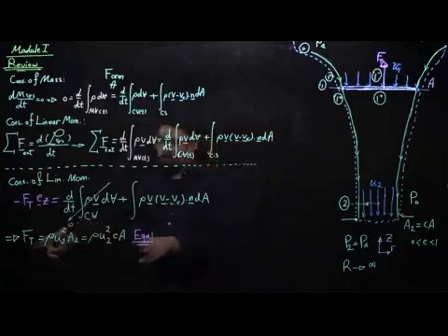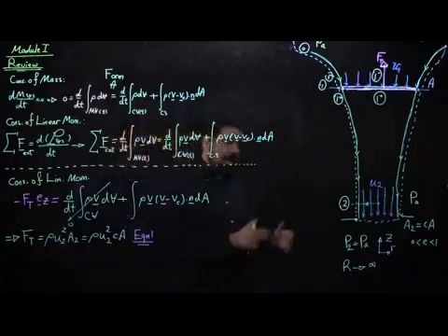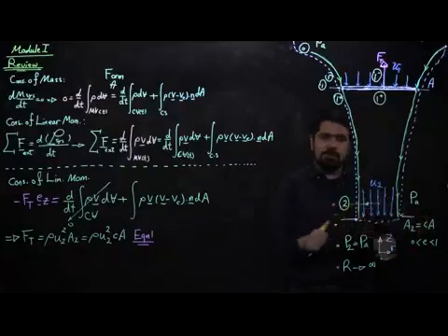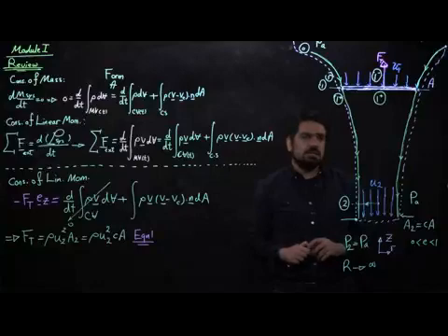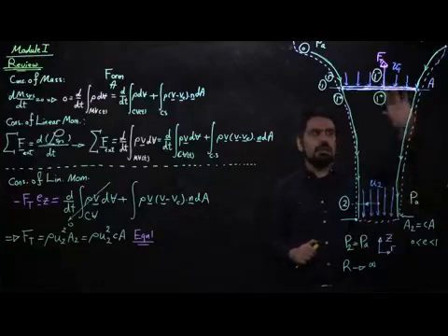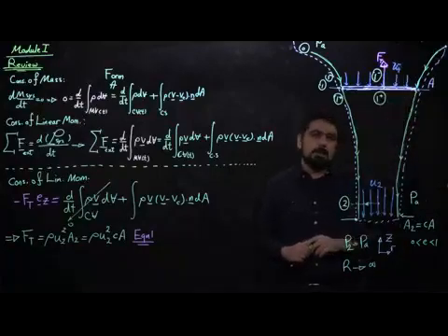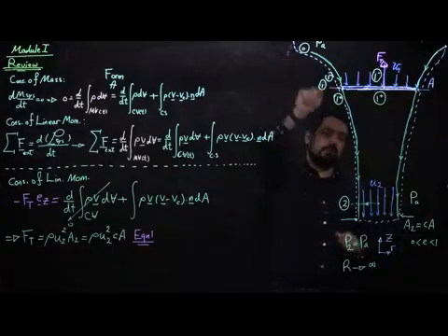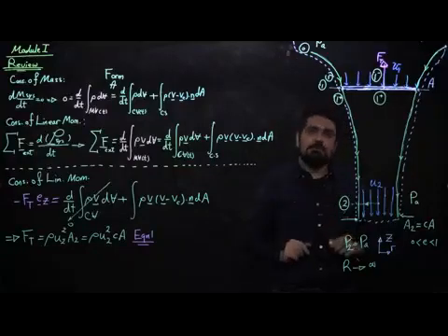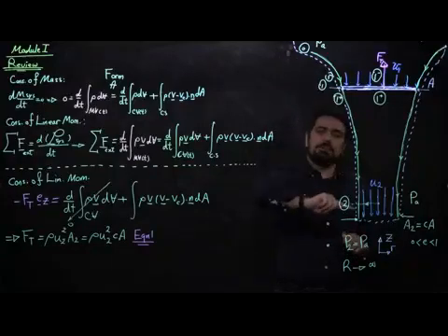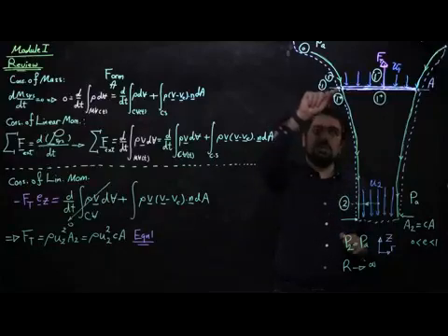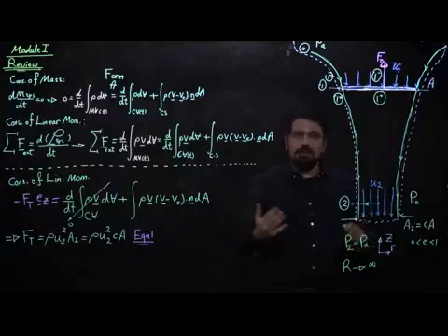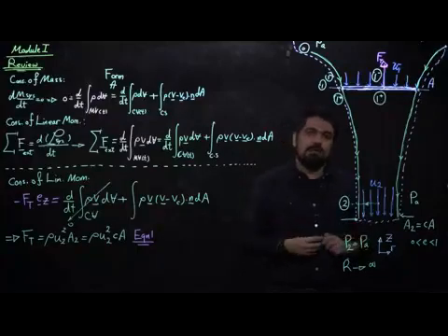Now that we have used conservation of linear momentum and used something like Euler normal to streamlines to talk about pressures, for example, in a cross-section, let's see whether we can use anything else to talk a little bit about connecting pressures between different points of this problem. Somebody may be tempted to say that, oh, I can use something like Bernoulli and then connect the pressure from here all the way to here. But we need to be careful. It's true that a streamline passes from this point to the other point, but this streamline goes through a blade that is giving or getting some work and energy to the fluid elements as they pass through it.